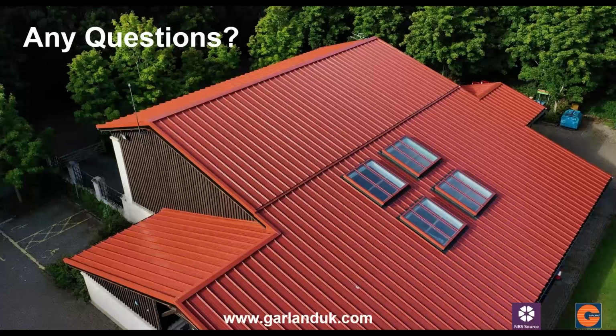But always look for that fire certificate as well, because in that fire certificate there'll be different build-ups that have been tested, and you want to make sure that's applicable to what you're specifying. So it might be just tested on a bit of plywood. Some will be tested on the plywood with a whole build-up that will be representative of your project. So you're designing out risk, and you've got a piece of paper to assure you that you're achieving B roof T4, regardless of what your build-up insulation type is, etc.